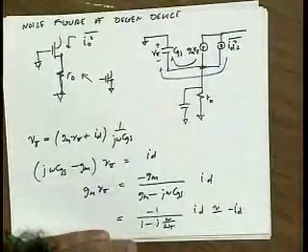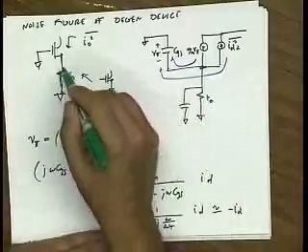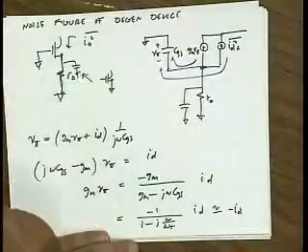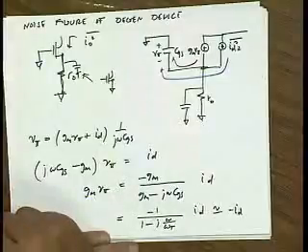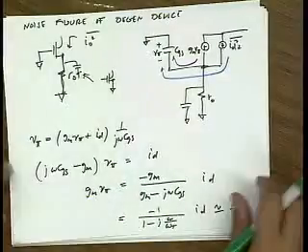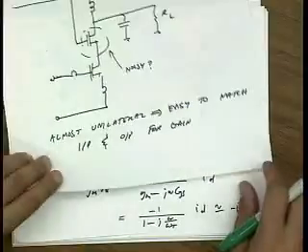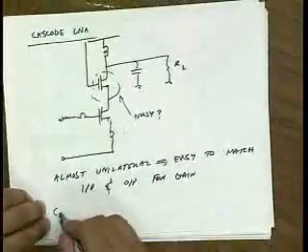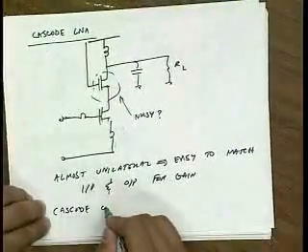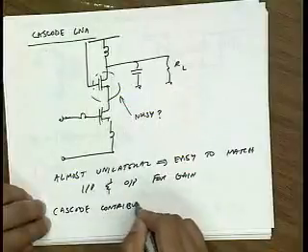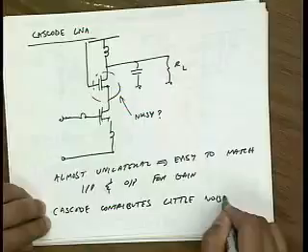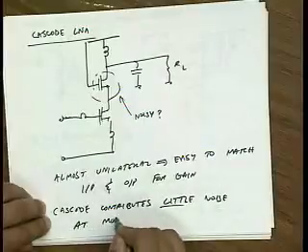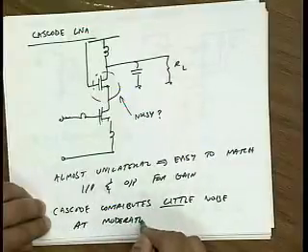So at really high frequencies, we'd like to minimize the capacitance on this node in order to minimize the noise contribution for this device. Okay? So coming back to here, we see that the cascode contributes a little bit of noise. Let's say at moderate frequencies.